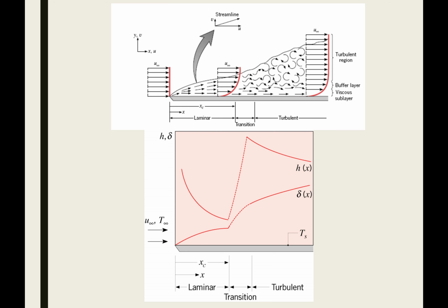Then suddenly, when we transition from laminar to turbulent, we get much better transfer of heat, because turbulence really helps heat to be transferred faster. So that combination of our boundary layer being relatively thin, plus all the circling and swirling due to turbulence, creates the highest heat transfer coefficient. And then once you've got turbulence and the boundary layer keeps on growing, your heat transfer coefficient starts to degrade again. Any questions here? It's all sort of just conceptual.